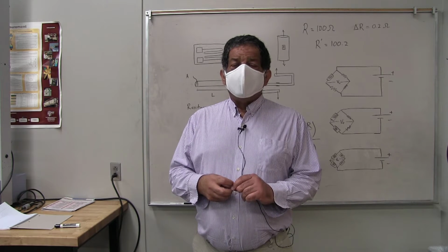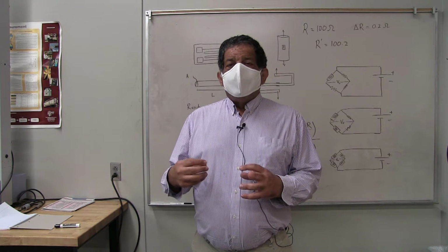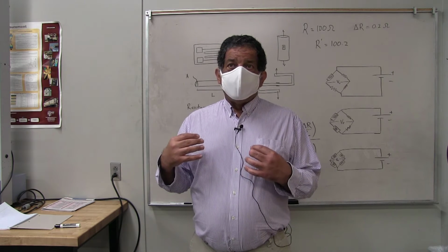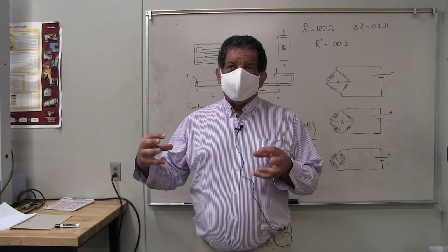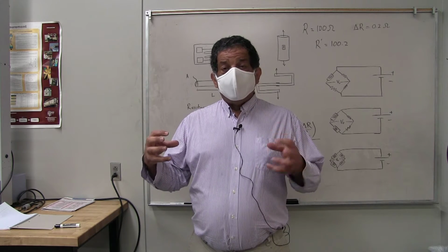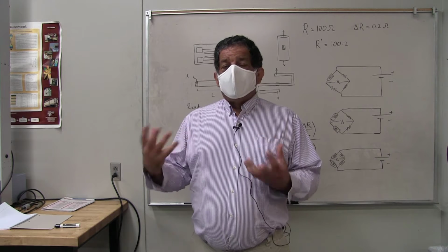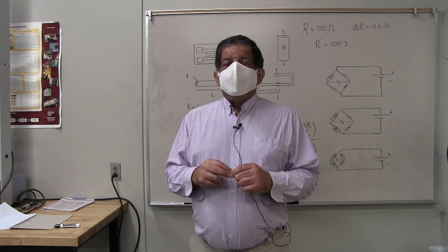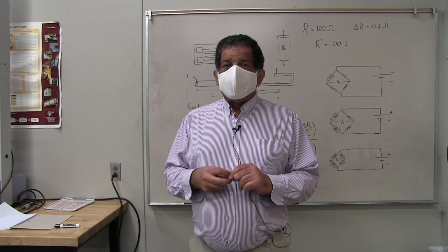And then later on in the lab, you're going to use a complex set of loads that you apply to a tube that is being deflected both in bending and in torsion, and then you'll measure a complex state of strain on that one using a strain gauge rosette.